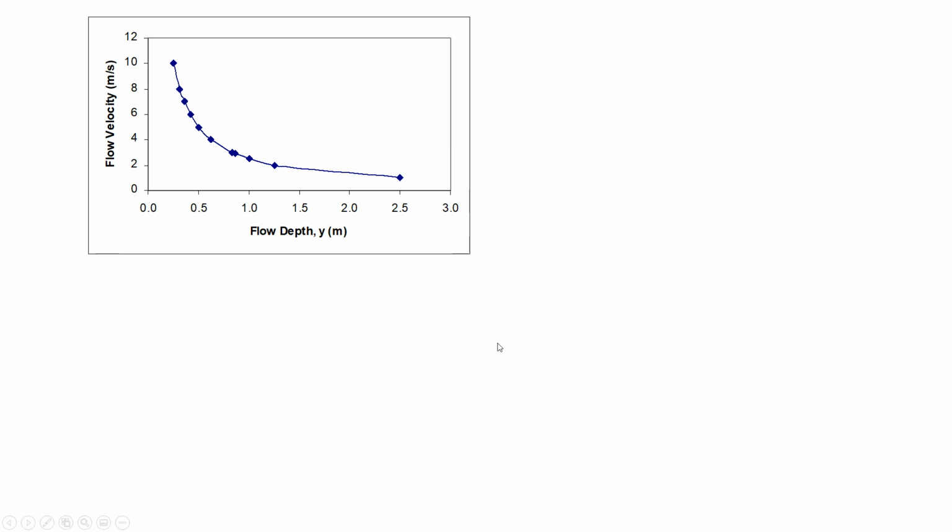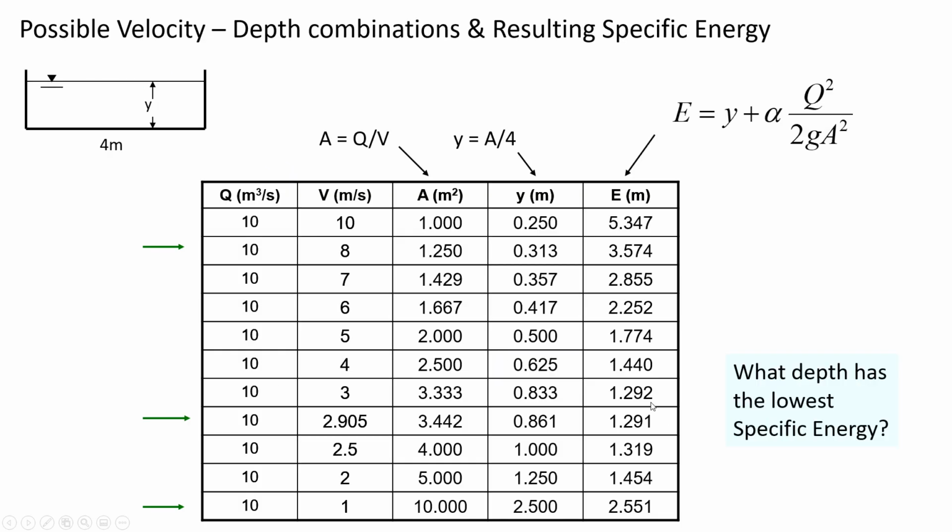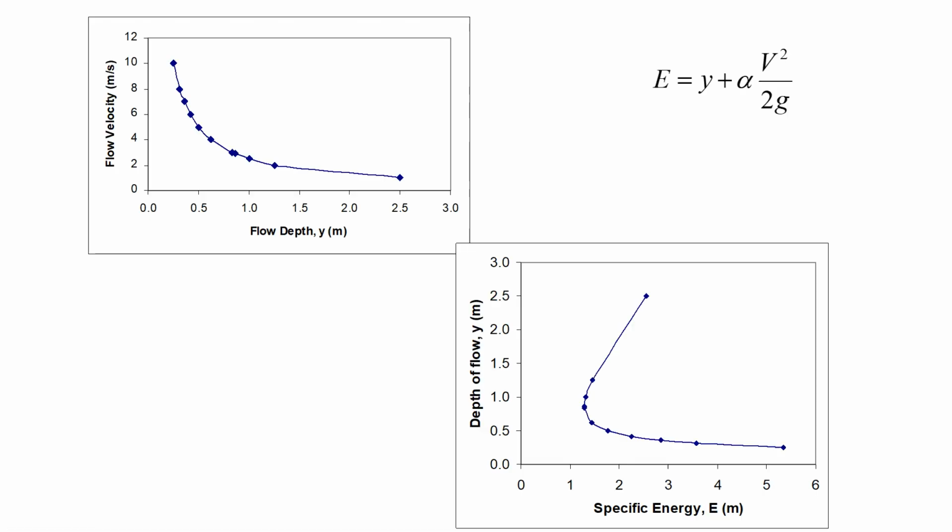So remember on this previous curve where we pointed out this is the lowest specific energy, on the graph, that's this point, furthest to the left on the curve. Minimum specific energy. And what it corresponds to is the critical depth. Do you remember earlier you classified flow as either subcritical or supercritical with the Froude number? Did we do that in fluid mechanics? Was this class? Yeah. You had a homework assignment where you classified the flow regime.